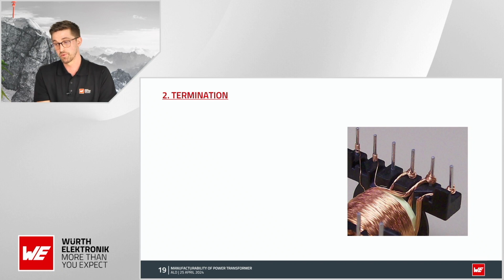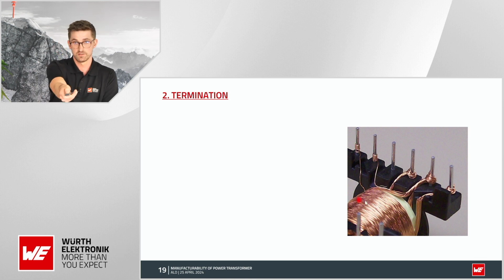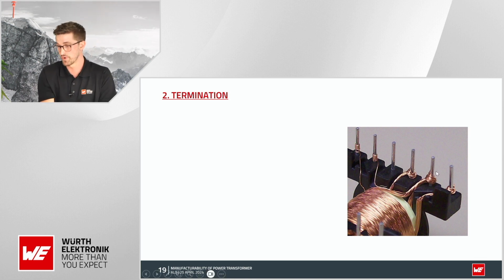The way we terminate the wires is crucial in the design of a transformer. What we can see in the picture is commonly seen on step-up transformers, where we have a heavy wire primary winding, here, on the same rail as an auxiliary winding, more on the left. Although the auxiliary winding generally does not require a large wire, it might be convenient to over-dimension it, to minimize the risk of being damaged during soldering.